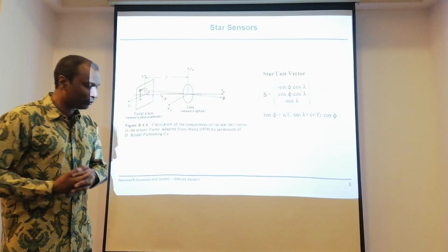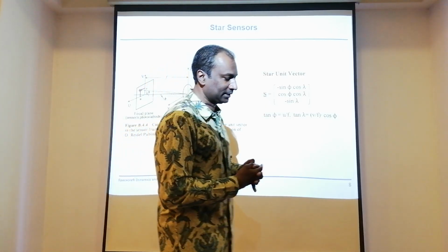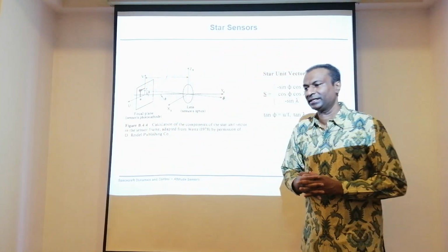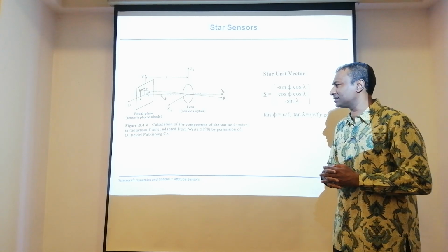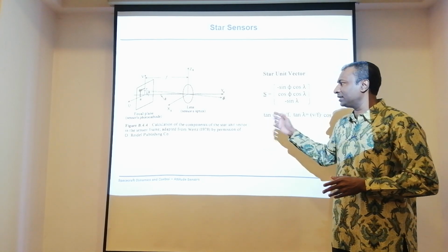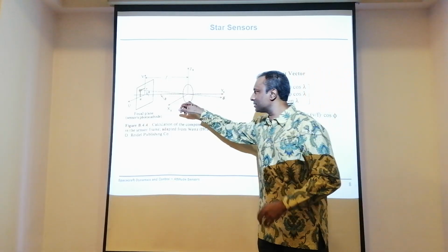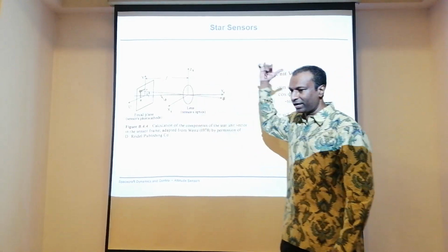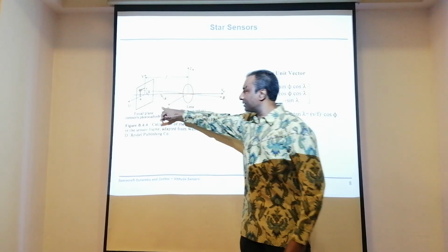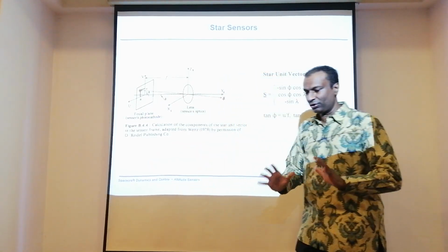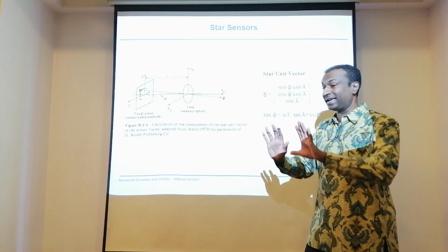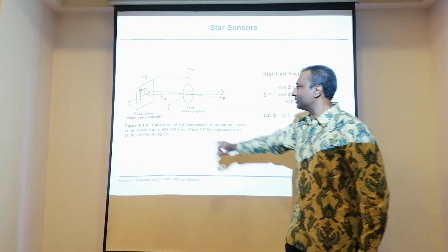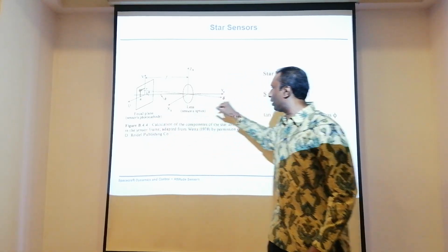Now, slightly more expensive sensors, star sensors. Not any satellite is actually going to fly star sensors. Importantly, the principal lens is actually going to look at your sky, and technically speaking, inside the sensor you already have a catalog of images to compare with what exactly you see.